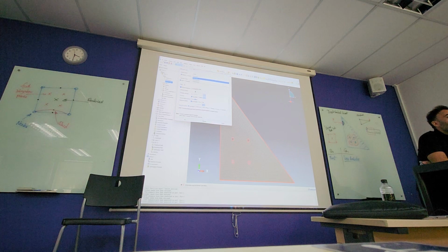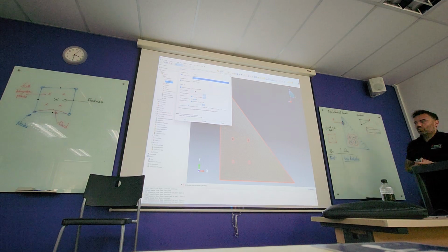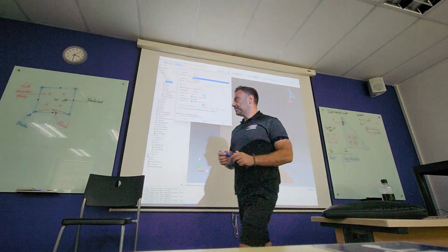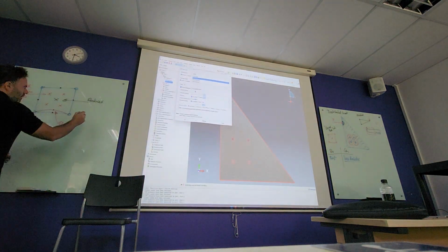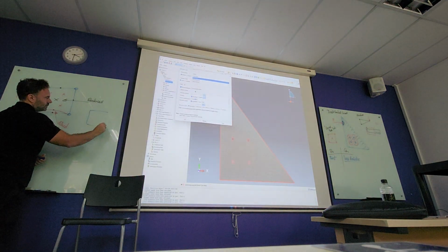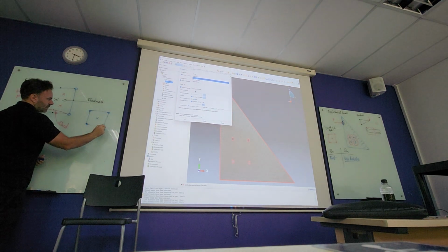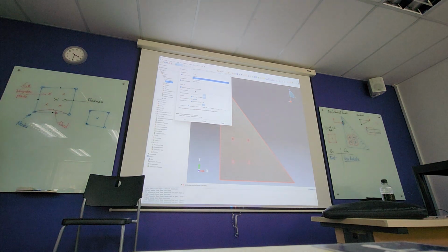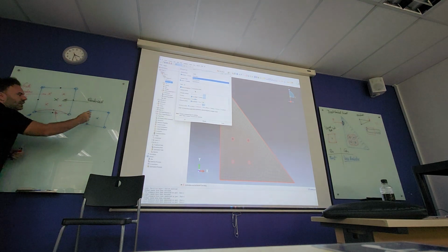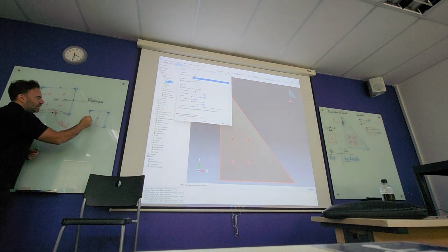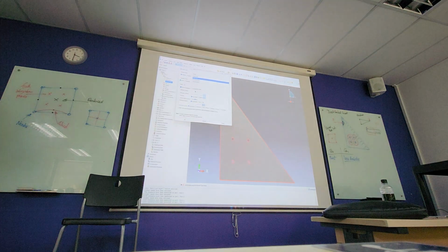Have you heard of hourglassing? No? Watch those videos. What happens is that if you go with the reduced integration, so the way usually it's calculated, Abaqus looks for changes in shape of those elements.